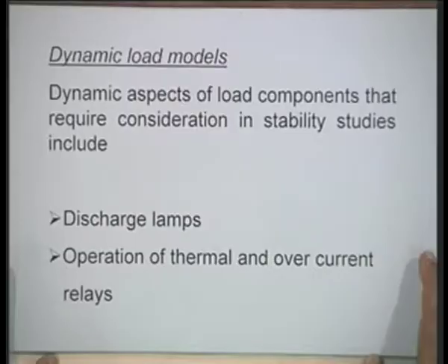Now we will discuss the dynamic load models. This is all about the static load models, and the justification of static load models is that whenever the magnitude of frequency and voltage changes, the new value of power consumed changes quickly. The response time is practically low, and therefore we can represent these loads by static models.